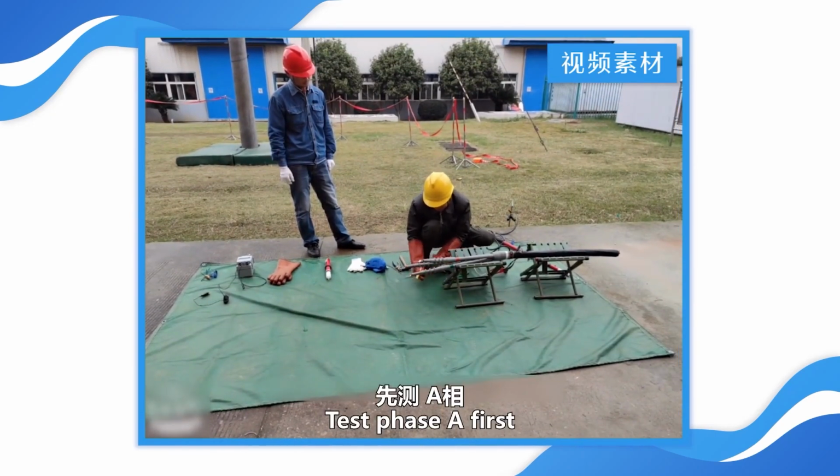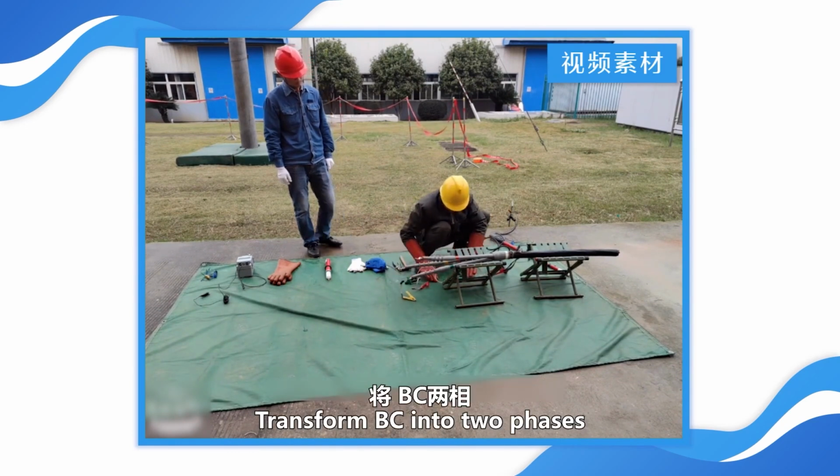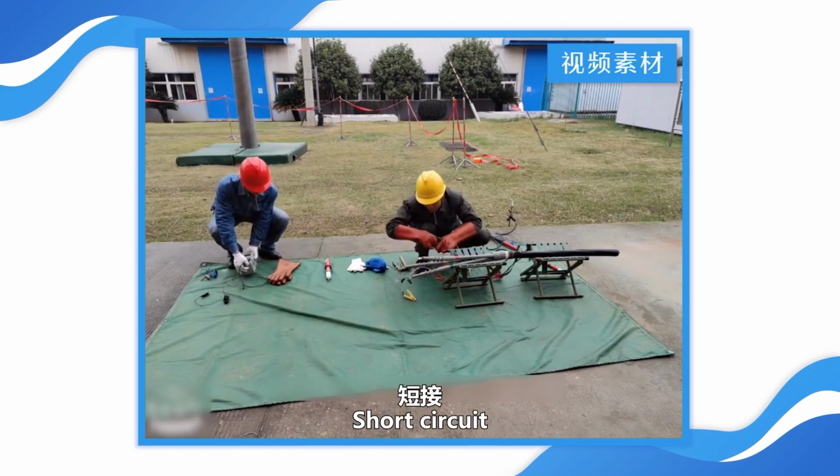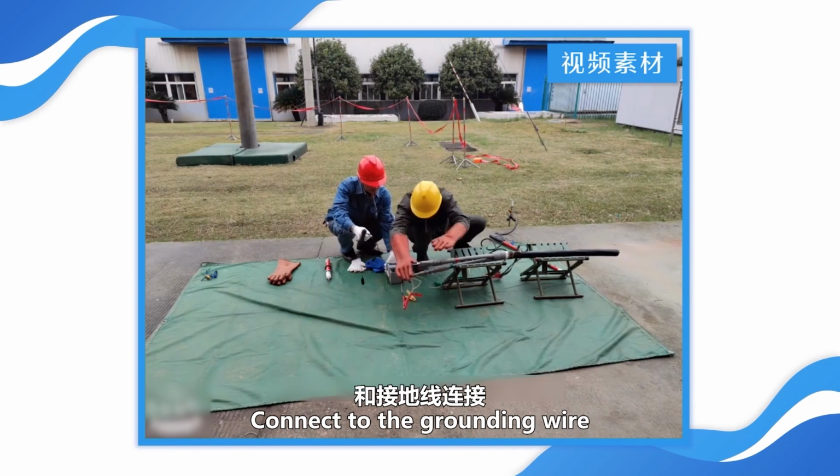Test phase A first. Short-circuit phases B and C and connect them to the grounding wire.